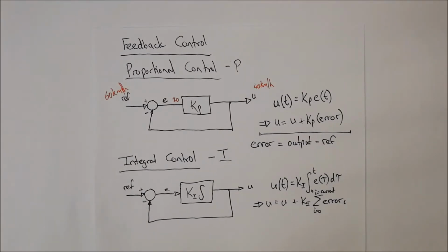Okay, so essentially what you're going to be doing is adding all the errors together as you're going along until you get to your set point value. And even at your set point value, your errors will be small. But keep in mind that this sum of errors is not the sum of absolute values of the errors. So sometimes your error could be negative, and then you need to actually subtract the value, and eventually that value will decrease.